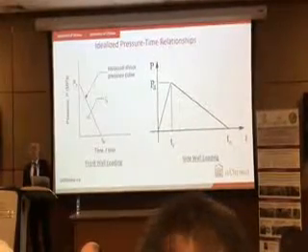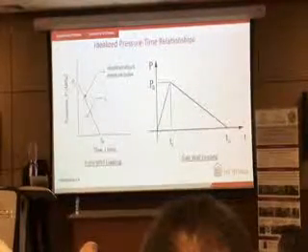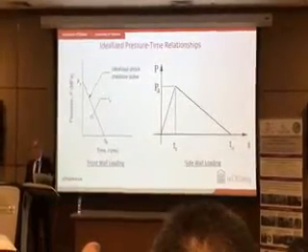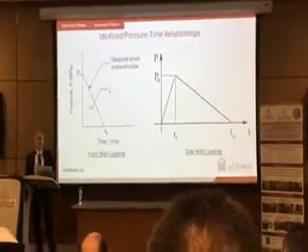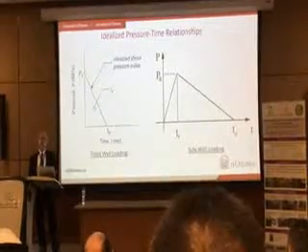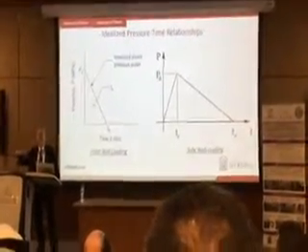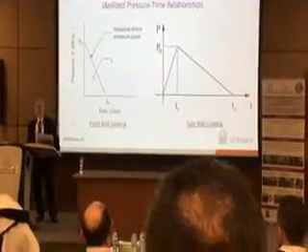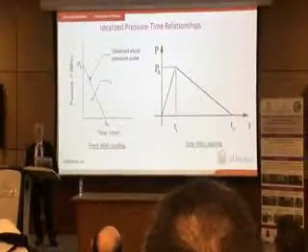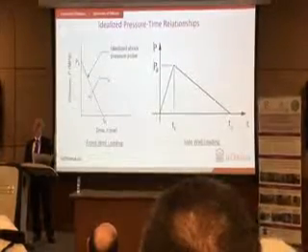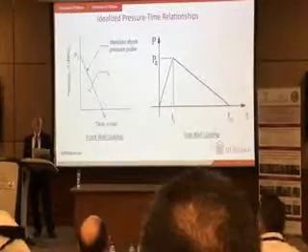Blast effect is such a low probability rare event. We don't want to split hairs. We don't want to give undue accuracy because we don't know whether it's 200 or 250 kilogram threat that we're going to face. It doesn't make sense to try to integrate parabola, hyperbola, although in my graduate class I make students do numerical integration as an exercise. But in design problems, we deal with these idealizations.